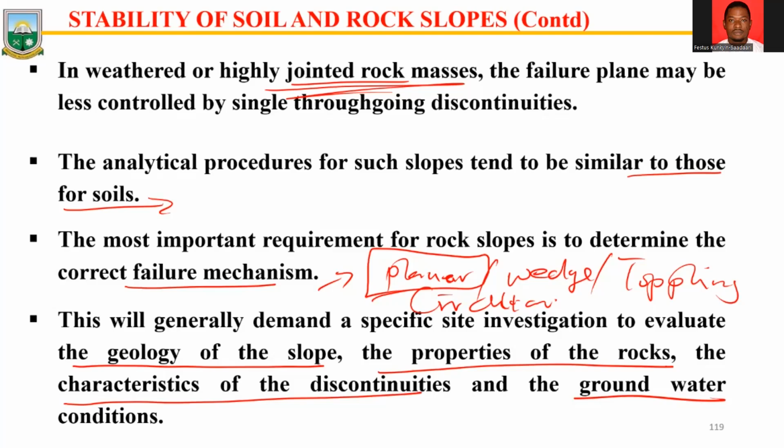So you need to understand the angle of repose of the material so that you can batter the angle very well. So when it comes to dams, usually it is about the angle of repose of the material and whether the material is capable of weathering easily.